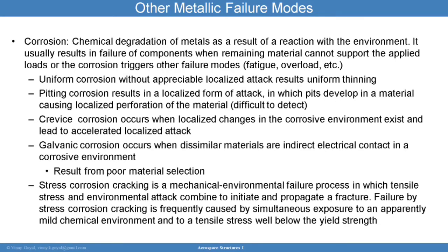So what is corrosion? Corrosion is the chemical degradation of metals as a result of a reaction with the environment. It usually results in failure of components when the remaining material cannot support the applied loads, or the corrosion triggers other failure modes. And in these events, corrosion can cause even other failure modes such as fatigue and overload.